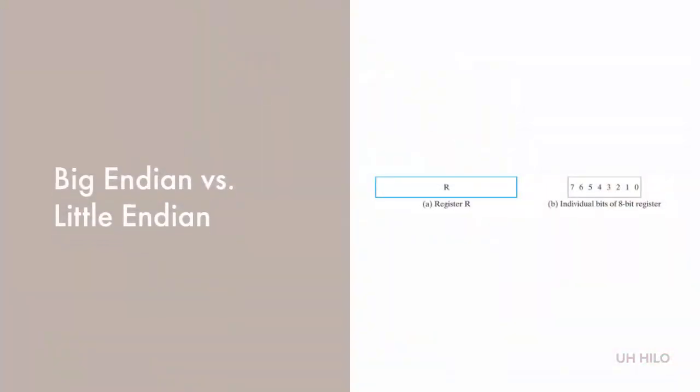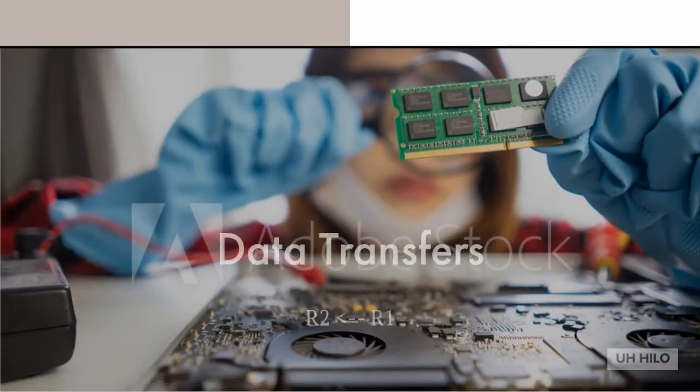The individual flip-flops in an input register are typically numbered in sequence from 0 to n-1, starting with 0 in the least significant position and increasing toward the most significant position. Since the 0 bit is on the right, this order can be referred to as Little Endian. The reverse order with bit 0 on the left is referred to as Big Endian. The most common way to represent a register is by a rectangular box with the name inside. The individual bits can also be identified as shown in Figure B.